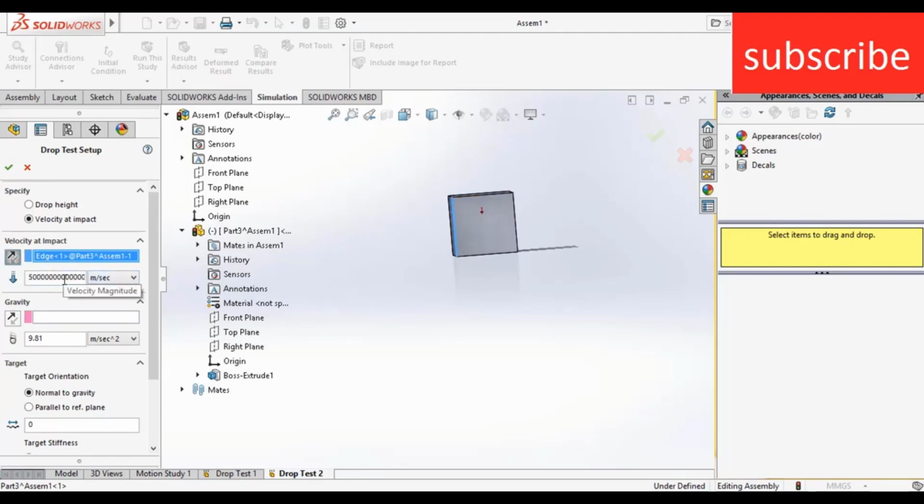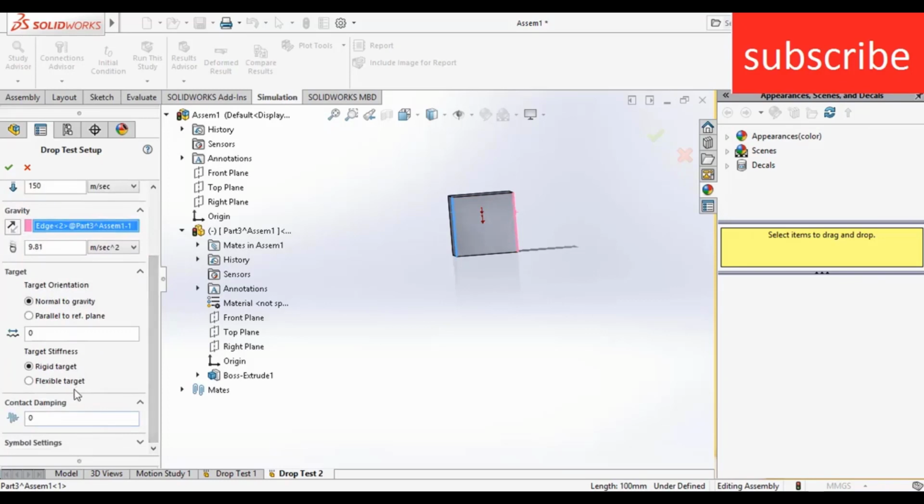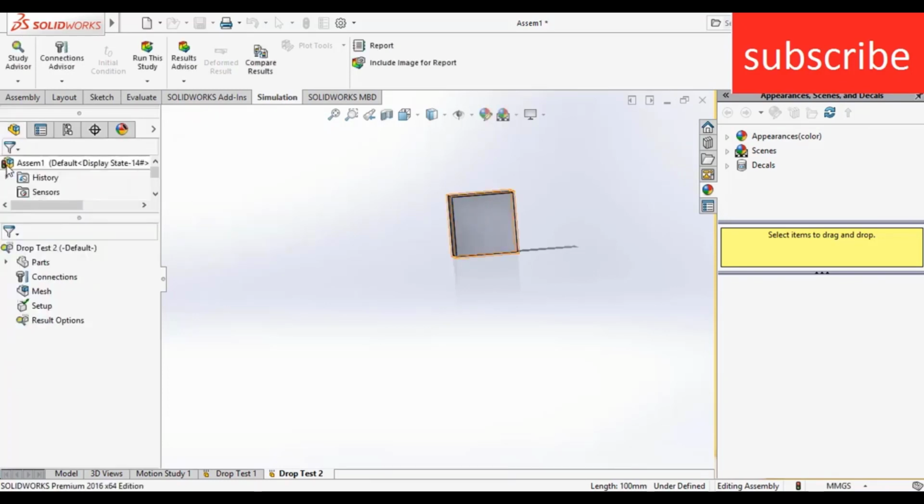And remember one thing, that drop test can do simulation up to a velocity of maximum 500 meter per second. Here you see this value, so we reduce this value to 150, and it's asking for the gravity direction. Again select this edge, make sure it's acting downward, and here it is, and click OK.